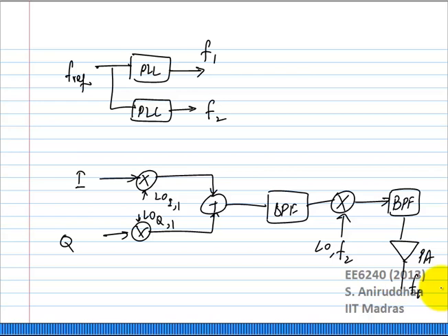Now, I'll give you an example. Either the magnetic coupling or the substrate coupling is a function of frequency. Let us say the output frequency was 2 GHz. At 2 GHz, the coupling was very strong because the capacitive coupling paths are very low impedance, right? And the magnetic coupling may also be stronger. But maybe the two PLLs are working at only 1 GHz each. That is an example, okay, where the coupling mechanisms are weaker.